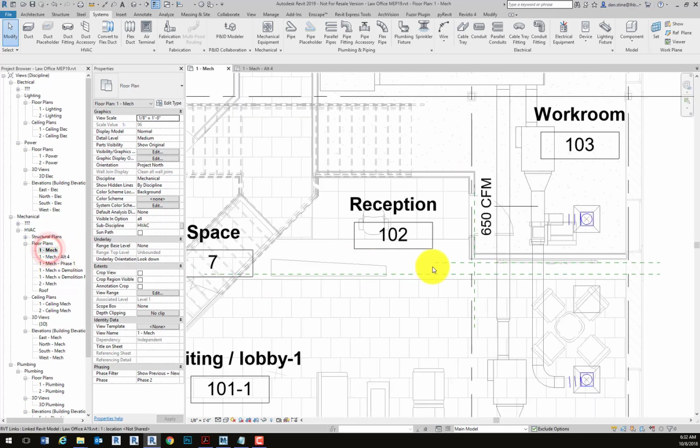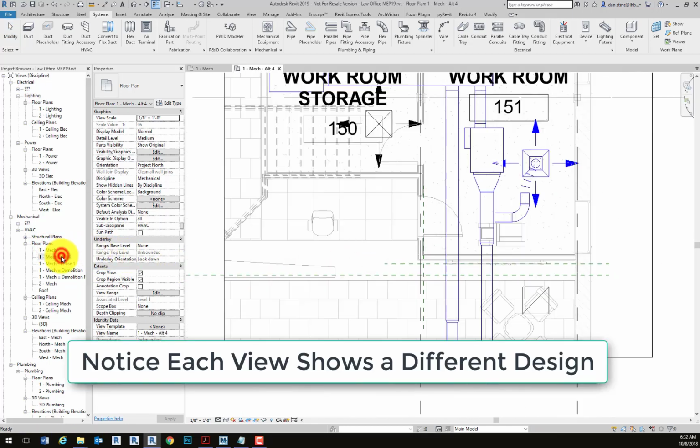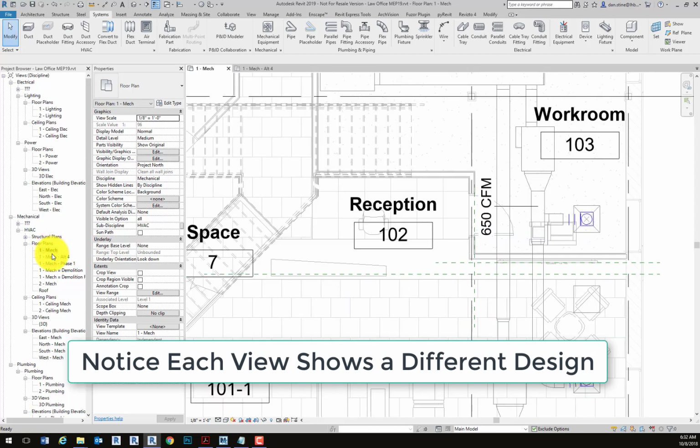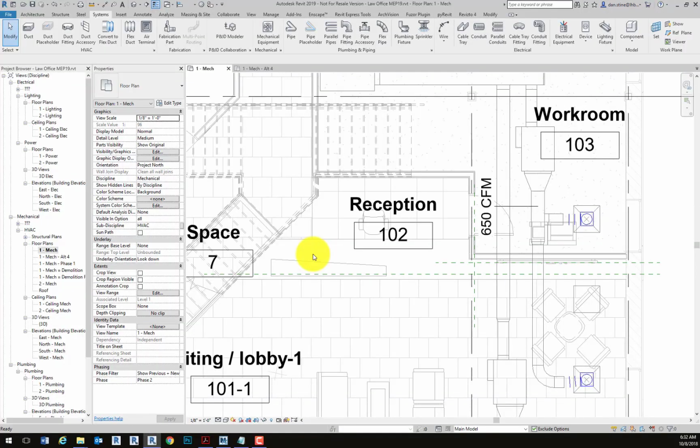It is possible within a secondary design to have loads calculated if there was the air terminal and the VAV box all in the secondary design option. You could get the loads all the way up to the air terminal, but any extra loads in an alternate would not really make its way to the air handling unit for the main project.